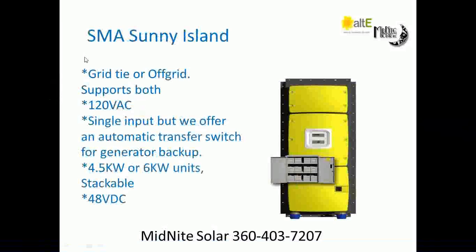It is stackable up to 4 units, and that is what is called a cluster to SMA. SMA themselves can do multi-clusters, but you get into the multi-cluster box, which again is going down the road of village power and a little bit more than we probably want to elaborate on in this slideshow. So for the purposes of this talk, we're going to consider the Sunny Island up to 4 units only. If you need more than that, contact us and we will work with you on that. It is 48 volts only.